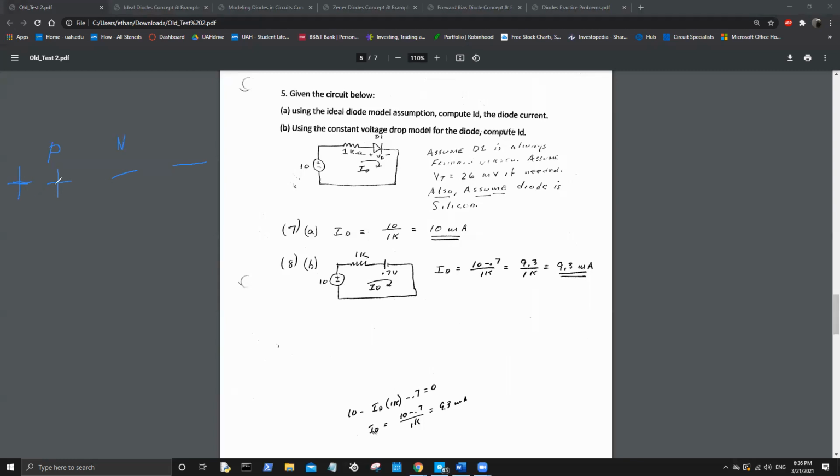Now, yes, these are pushing together, and this will close the depletion region by forcing those charges together, allowing stuff to flow. But here's your problem: you need a certain strength of electric field to force this shut. Once you reach that strength, charge immediately flows. So on your voltage to current graph, it'll be like boop, boop, boop, boop, it'll go to 0.7, and then it'll just go.